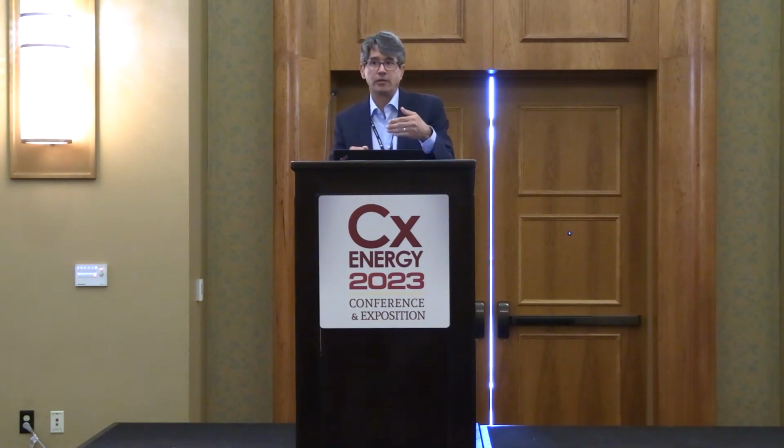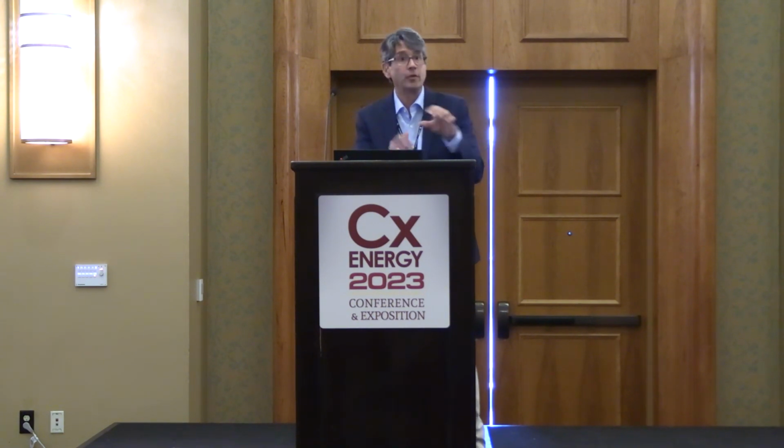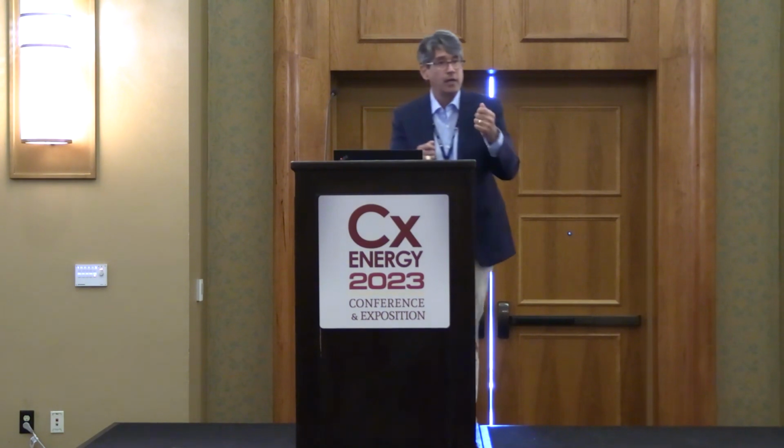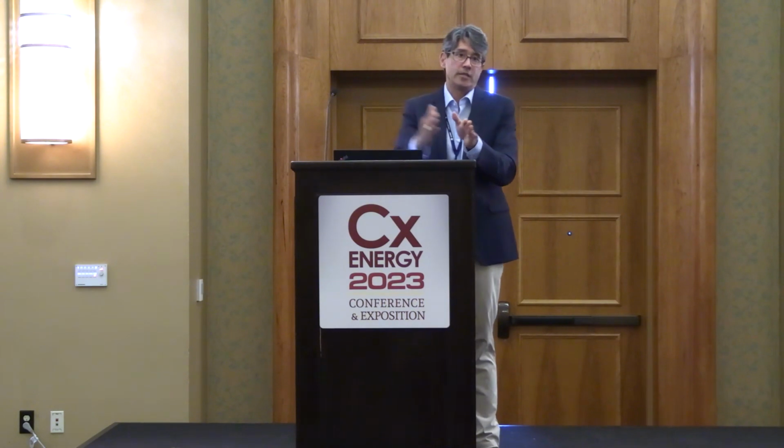The other piece of it is you can even look mechanically. Rooftops are always my favorite equipment. Outdoor air on a rooftop. One, trying to measure it, whole nother caveat, we'll talk about that in a little bit. But two, a lot of times they're gear driven, multiple gears, and you can go out there and grab that outdoor air damper and move it a half inch, if not more. Same thing with even the damper actuator in the shaft. So you set a minimum position for that outdoor air damper, and you've got that set up, but yet the next time it opens all the way in economizer or something, it's very seldom coming back to that same position because of the slop and the damper play or the gear play.